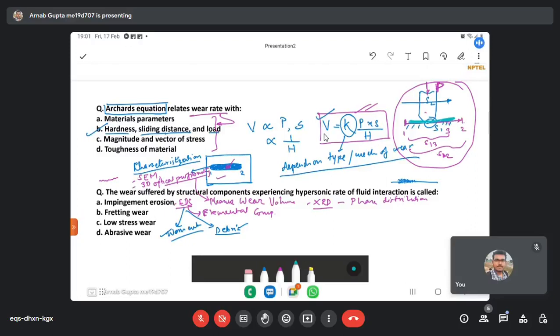And you are seeing that particular phase or that particular element is helping you in reducing the friction between the two surfaces. It is reducing the coefficient of friction. Then you can say that yes, we can choose this particular medium or this particular surface coating. That even after breaking or degrading, it is sacrificing itself, but it is leading to a reduced coefficient of friction.